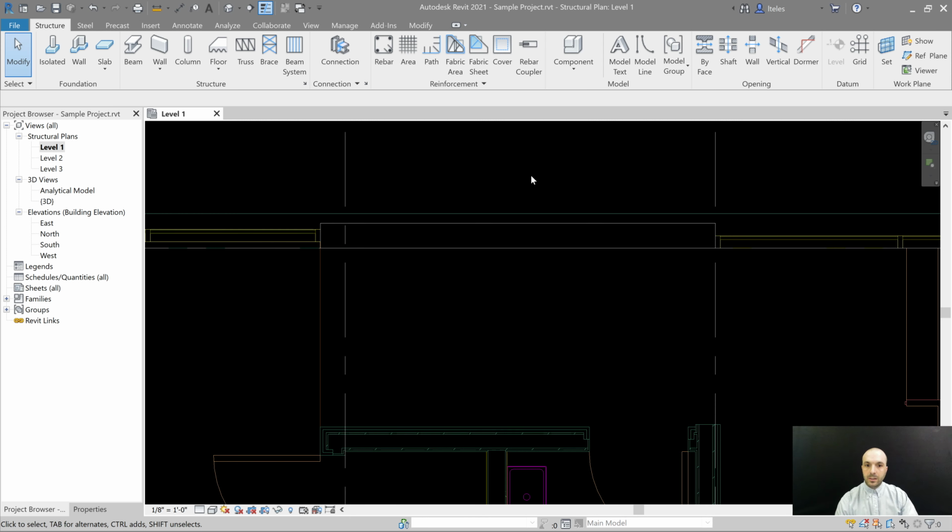All right, so now we have an idea as to how our wall is looking. We have something that we can view. Always keep your 3D view open when you're modeling. There are cases, like right now, where we are modeling in a plan view in level 1, but you always want to see what it is looking like in your 3D. Because if something looks off, at least you can diagnose it now. All right. So let's go back to plan view, and let's start adding more walls.